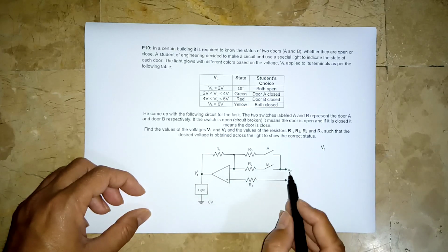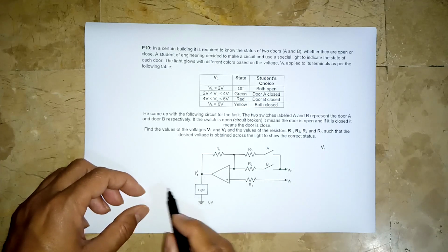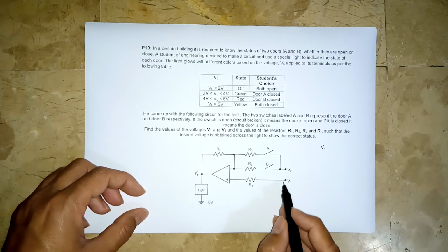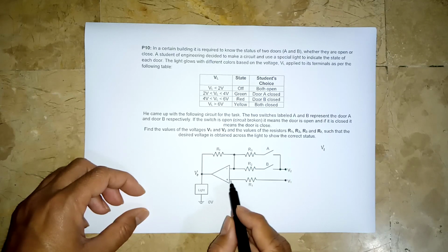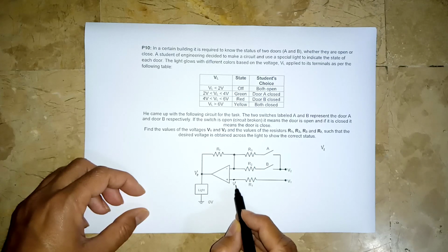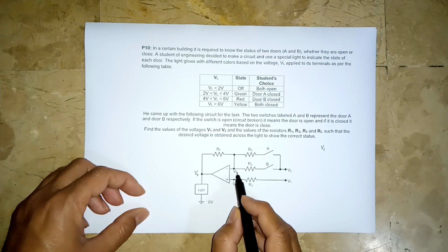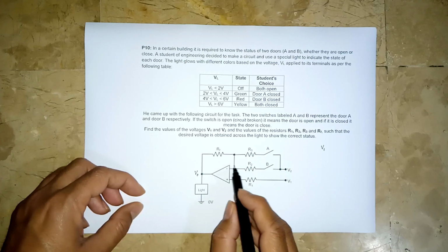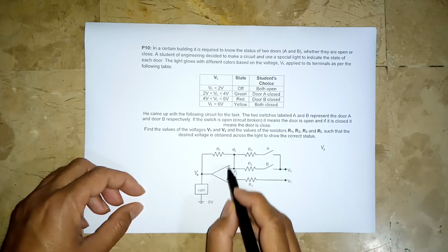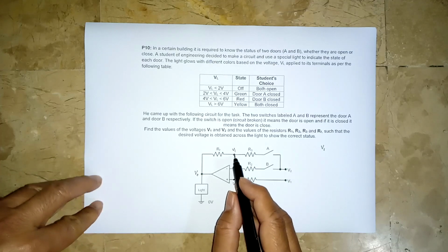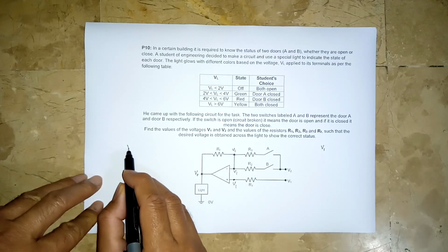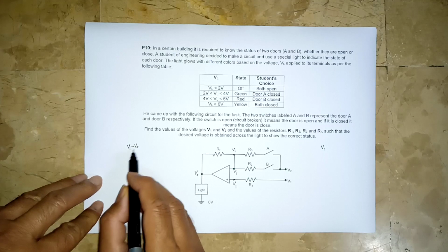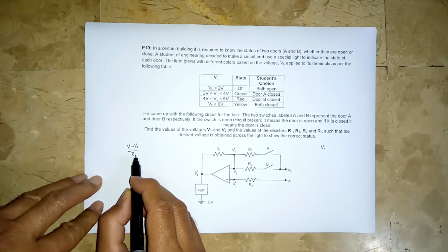How would VO depend on V1 and V2? If we can come up with an expression, which we obviously can. Just looking at this circuit, we know that whatever voltage we apply here, no current is going to flow in here, and we are going to get V1 here. So whatever is V2, this will be V1. So if we apply the node voltage analysis (NVA) equation here, we can write V1 minus VO over RF.